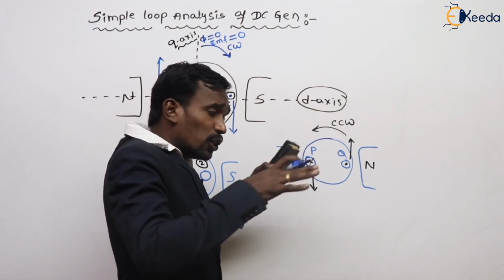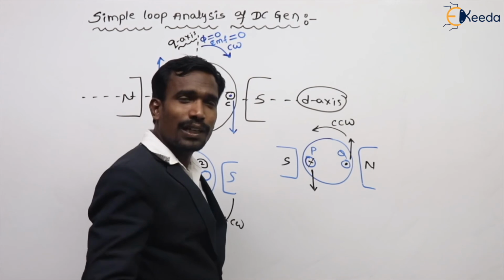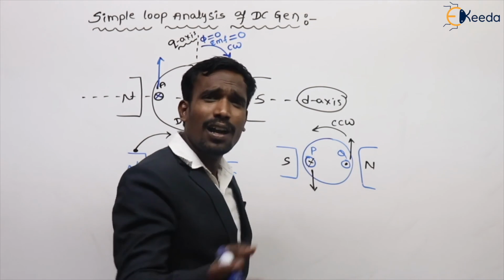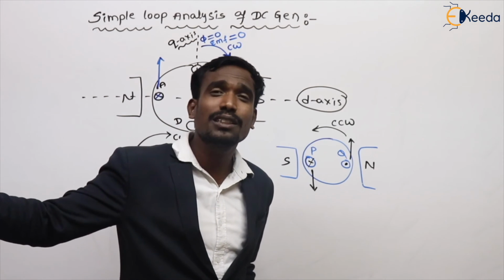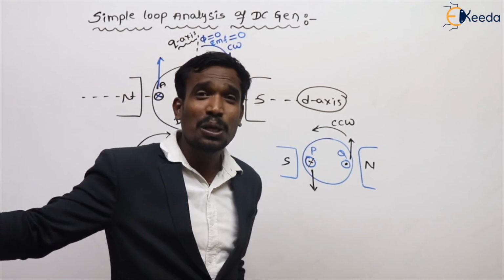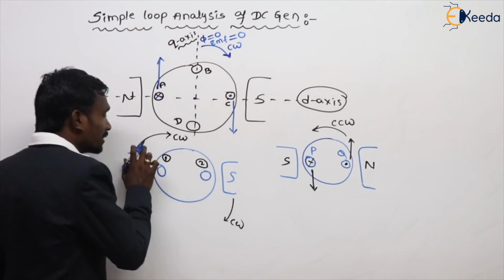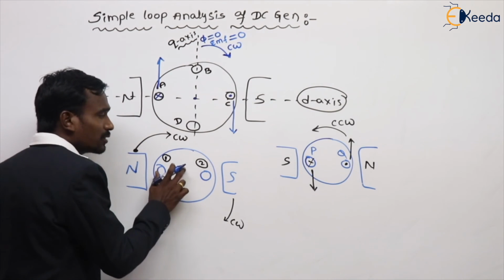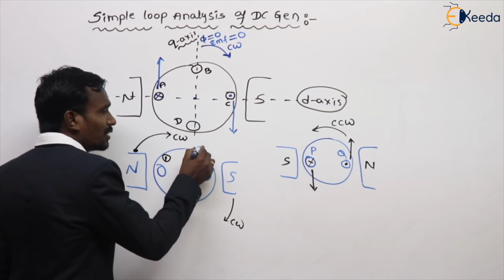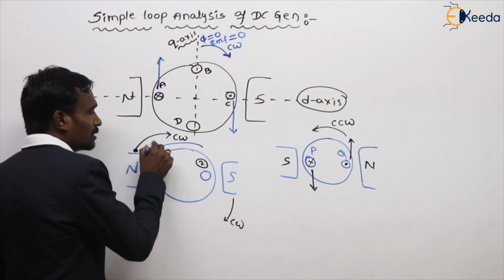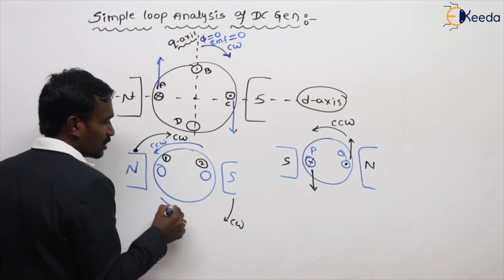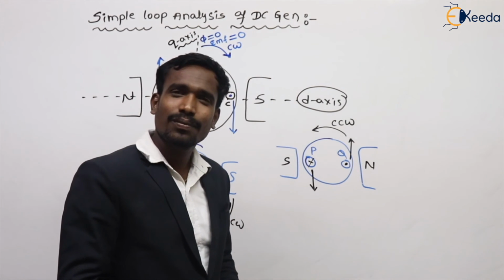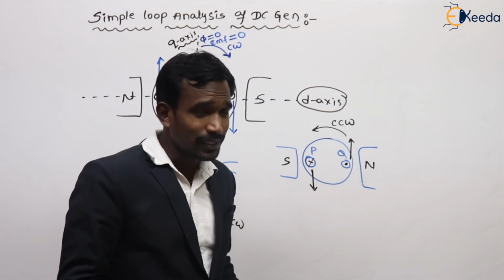But if you assume that you are stationary, what about the buildings? Do the buildings come with you or away from you? Opposite direction to you, right? Yes or no? So here, if this is stationary in your assumption, then the field rotates in the reverse direction. Nothing but now my rotor rotates in counterclockwise direction. This we have to assume here. Is it okay? Yes or no?